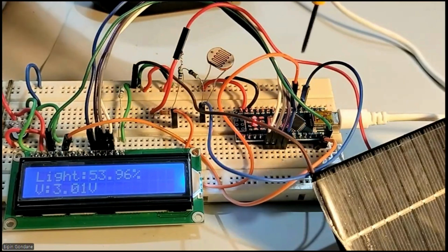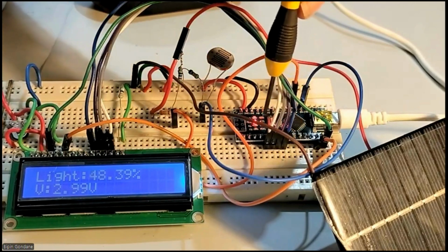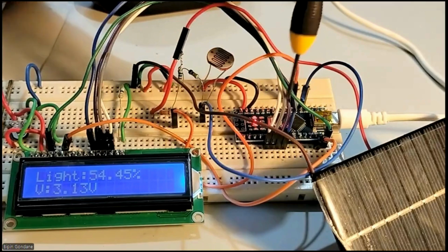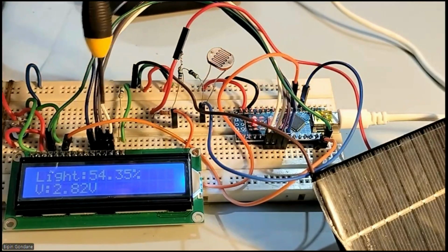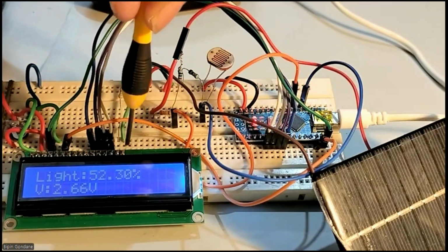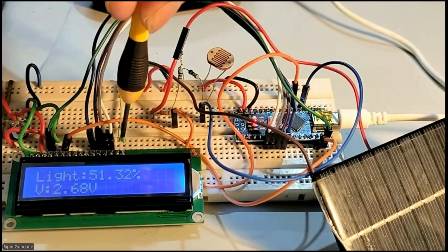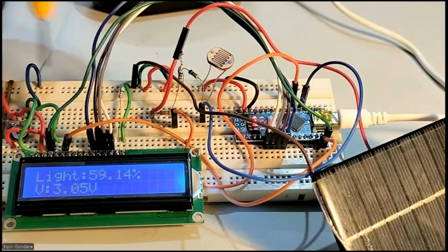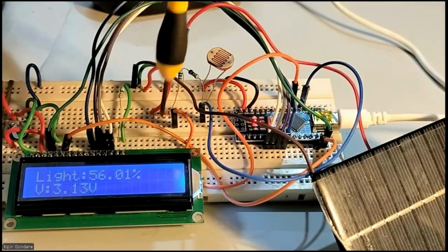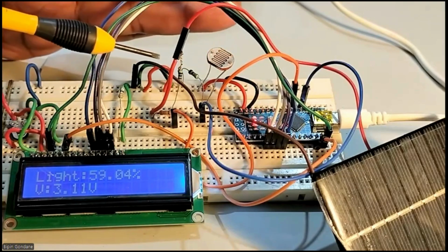Okay. So on the Arduino Nano, the two pins 11 and 12 I have connected over here, and these are the characters, and D5 to D2 are connected respectively to the D4, D5, D6, D7 of this. The last two pins are for getting the light on your display. The last one is ground, and after that you have a supply voltage through some value of resistor, up to 1K you can give. The lights will be on for this. Okay, so the display connections I have told you.